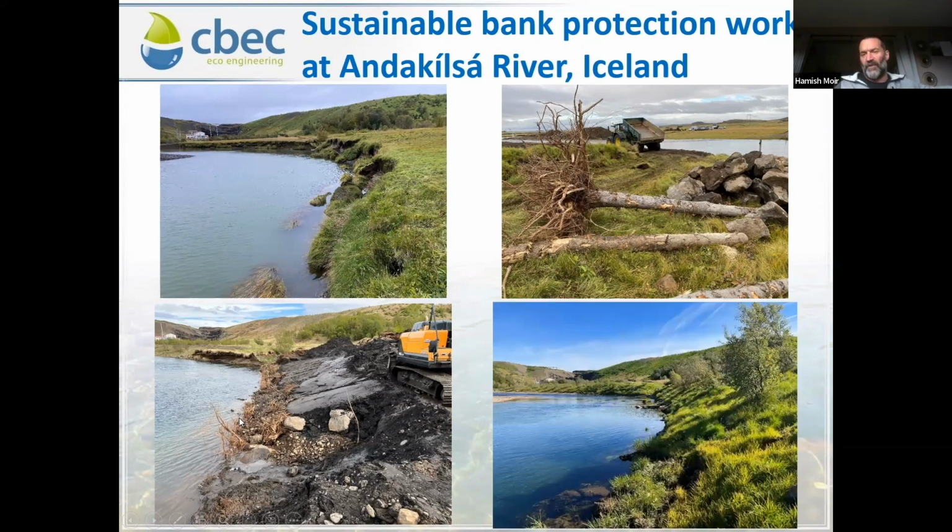This is about 3 or 4 months later. We've got this reprofiled bank with a stable angle. The turfs have really taken off. They're growing well. And we also, really luckily, the landowner was willing to give us these juvenile trees that were sitting in behind the bank here. And we could take those, we could dig the whole root structure up with the construction machinery and just transpose them directly into the bank. So immediately their roots are growing and providing this binding structure to the bank, which is a really excellent way for kickstarting this natural regen.